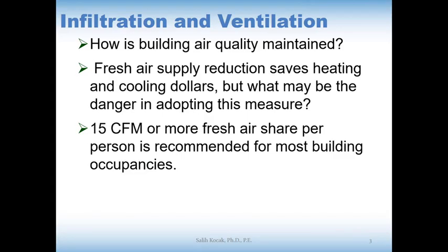So how much fresh air do we have to supply? This is the question now. So actually not us, but the authorities are saying that 15 CFM, cubic feet per minute, is recommended.